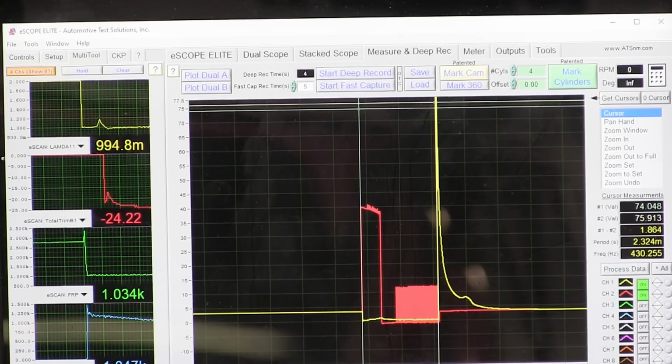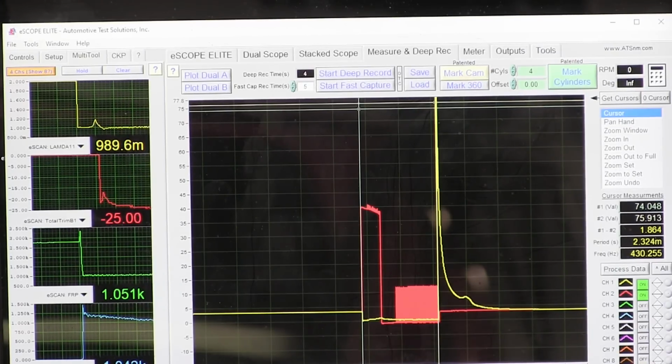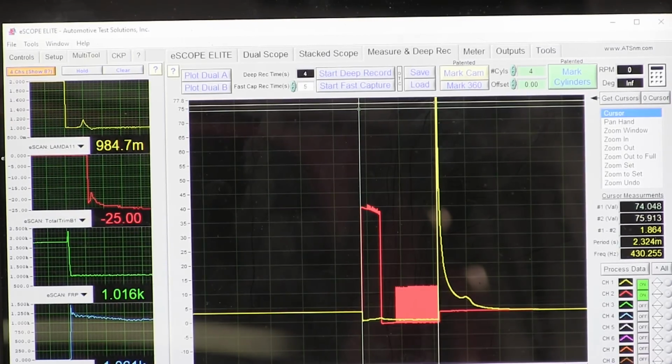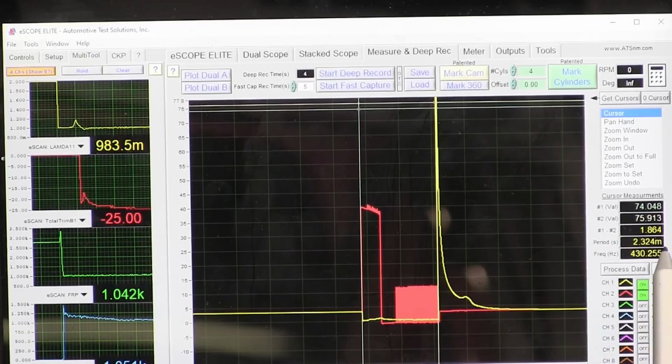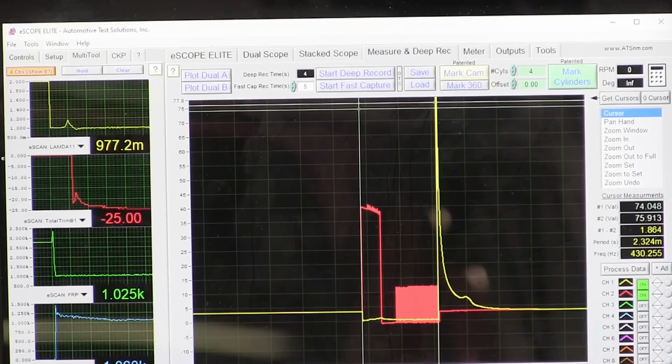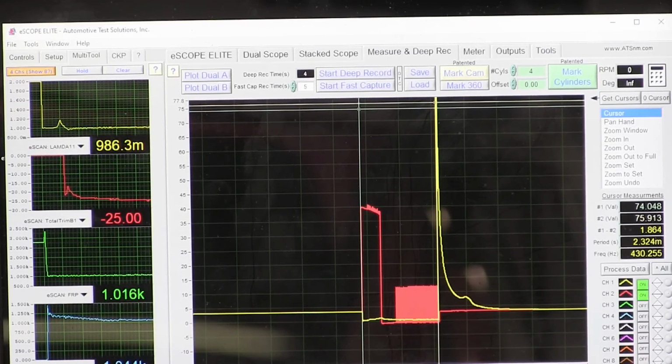Okay, so the injector on time is on for 2.32 milliseconds. Now for a cold start, that's not all that bad because the engine has not been run. It's still a lot of time, but if it was hot and I had that much like it did before where we had 1.4, that's just too much.